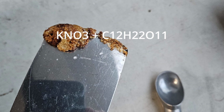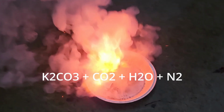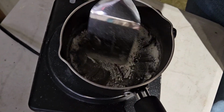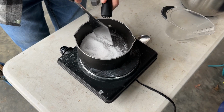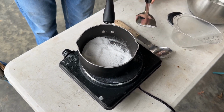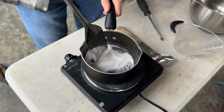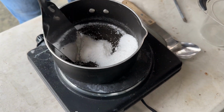When this mixture combusts, it creates potassium carbonate, carbon dioxide, water, and nitrogen. The last three of these products will be in a gas form, and is what composes our exhaust product. Sugar propellant is relatively easy to make. The emphasis in that sentence is on relatively. Really, the only thing that one needs to do when making this propellant is melt the sugar around the potassium nitrate. Since sugar has a lower melting point than potassium nitrate, it will be the only thing that melts, and you can encapsulate the potassium nitrate in sugar, thereby creating a good fuel and oxidizer blend.